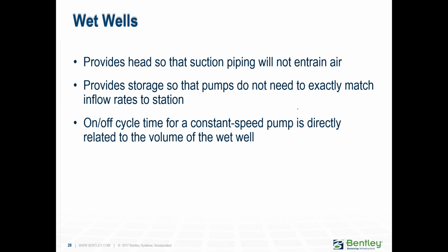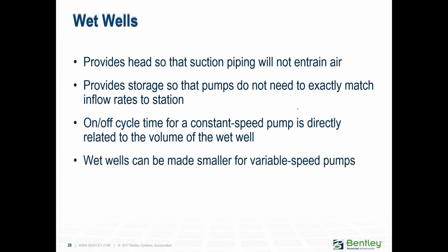And how big of a wet well does it need to be? Well, how many times do you want to turn the pump on? And every time you turn that pump on is going to cost. So do you want to turn it 100 times in a day, or maybe only 5? It is all directly related to the volume of that wet well, how big you're going to make it.